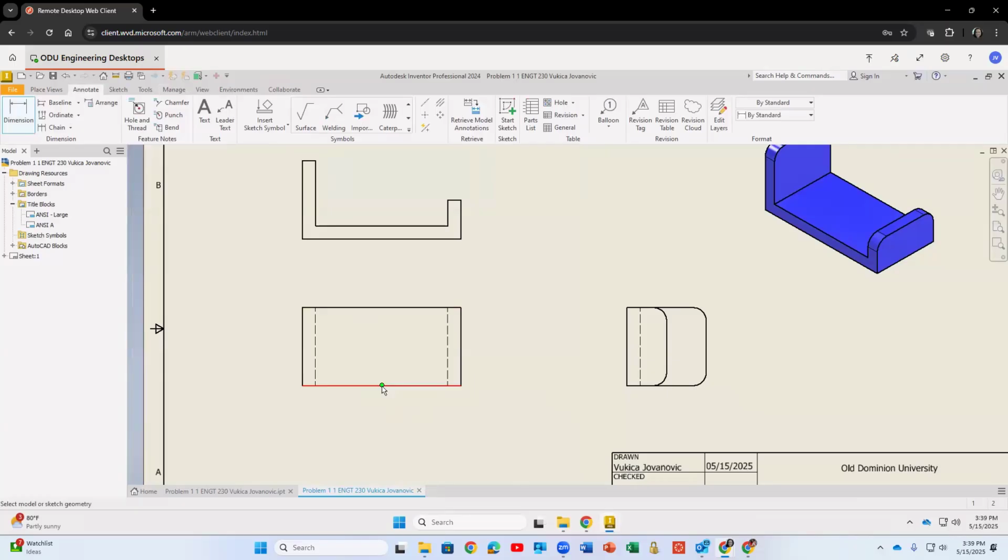And then I would just add, so you will always add like maximum dimension. So let me do dimension from here to here, left, left, left. Okay. Dimension from here to there, left, left. Okay. Now here I can put all these fillets. So if you don't want to dimension on every side, because this is kind of symmetrical part, you will tell that to the program by adding this symmetry line. Then I know that this is symmetric part, so I don't have to dimension on both sides.